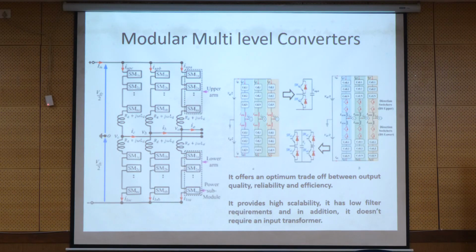One parameter is the THD calculation. If you maintain THD at less than 10%, you will say that your inverter module is working perfectly and can be applied to the application. But THD is the only parameter that we have to take into consideration.